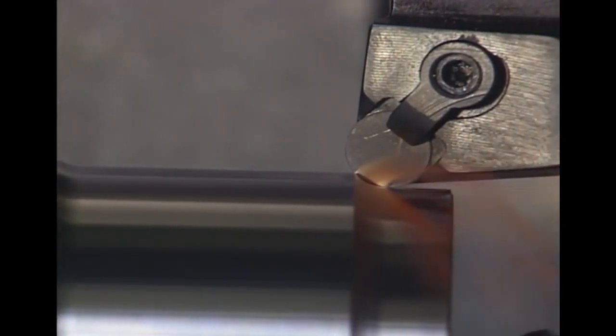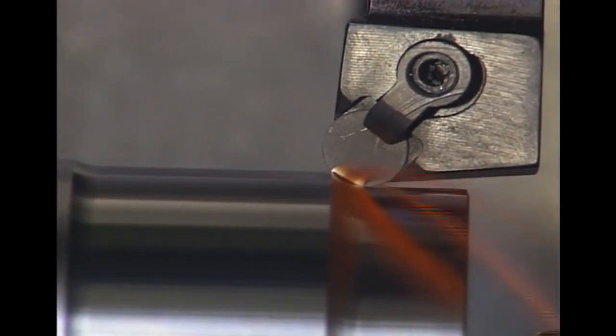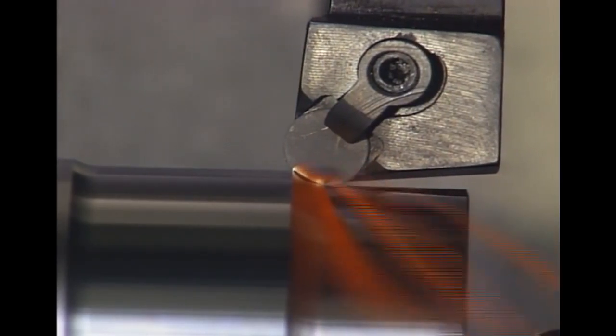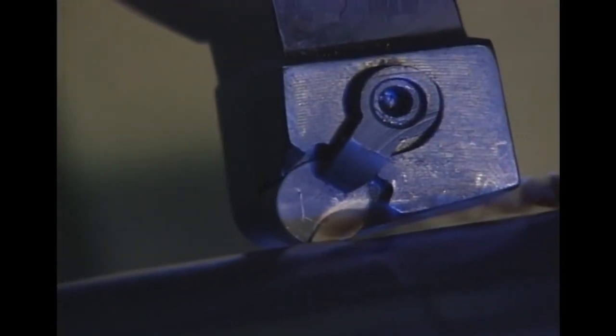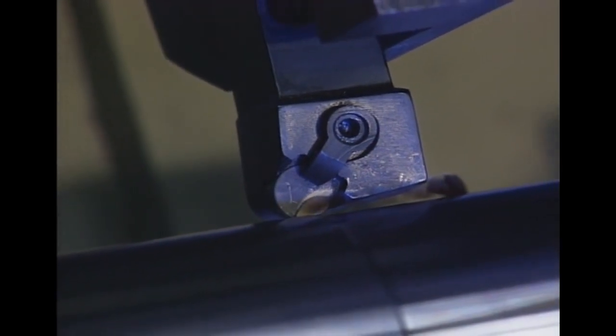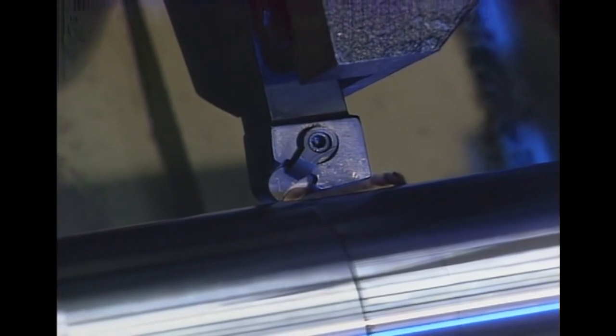Cubic boron nitride, or CBN, the second hardest material after diamond, is used to provide long tool life in machining very hard, tough ferrous materials, hardened die steels, alloy steels, and hard-facing materials. CBN is a hard, brittle material requiring cutting-edge preparations to suit application needs. Other techniques are utilized to protect the cutting edge, such as the use of a lead angle, where possible, and a strong shape, such as round or square, are recommended.